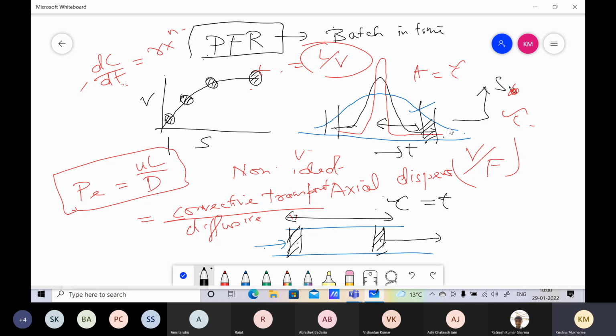Because the more there is axial dispersion, and obviously that makes sense because as we have this PFR becoming larger and larger, you are essentially reaching tank in series. As you know that one of the models that we make for PFR with axial dispersion is tank in series model as well. And the number of tanks in series makes it sharper and sharper. And as you know that in a CSTR, the conversion rates are lower because the reaction is a function of S.